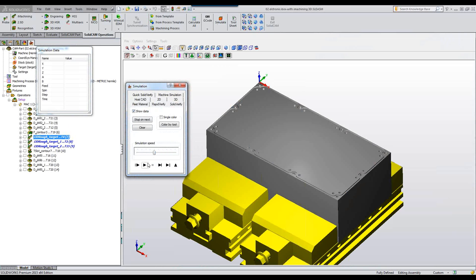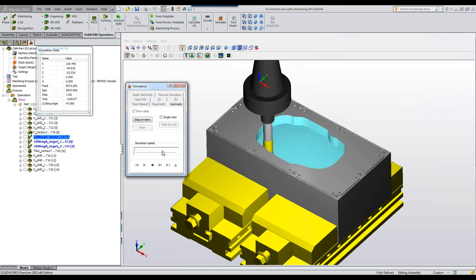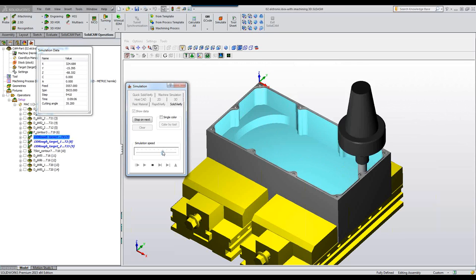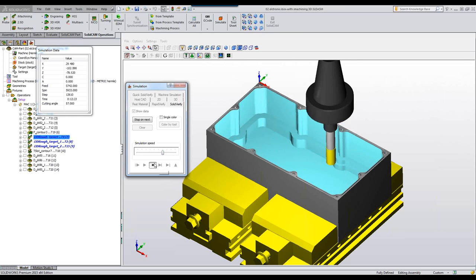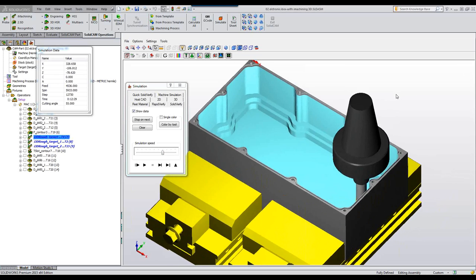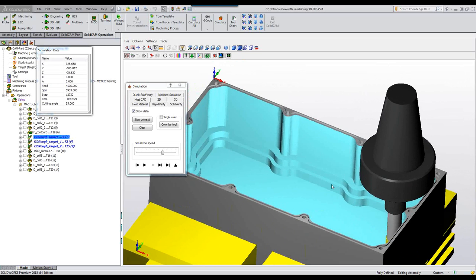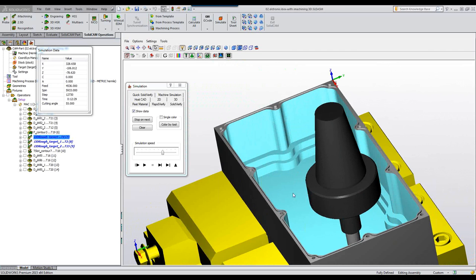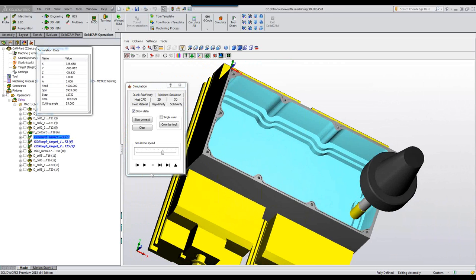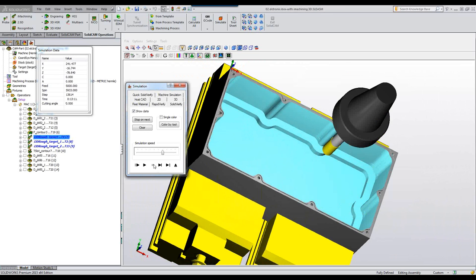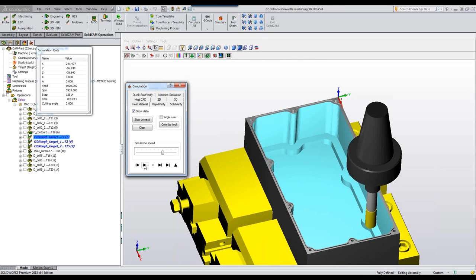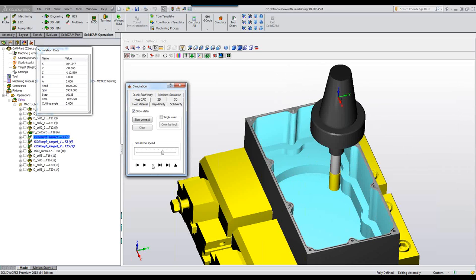It starts off very similar to the way the other one started out, doing those exact same spiral cuts. But now look what happens when it went further down and it got too close, it got to the area where it can't go any further in. It actually moved itself away, so this way it's clearing away all of this material with that larger end mill. Okay? Taking a look further down, you can see how it's actually machining all of those areas itself. Very bottom over there as well.